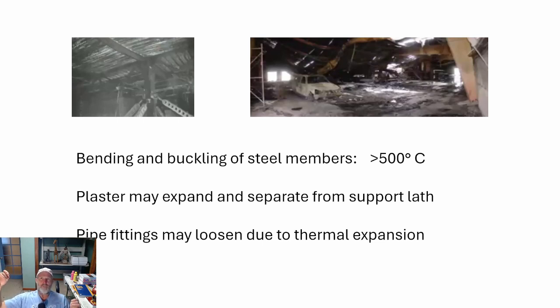What you'll see is a different rate of heat transfer into the bottom flange, fully exposed not only to hot gases but also to the heat flux. You'll have a different heat expansion there than on the top flange because you're losing energy to whatever it's in contact with. And that creates greater expansion on the bottom flange than the upper flange, and that creates a smiley face. So that's another feature of deformation.